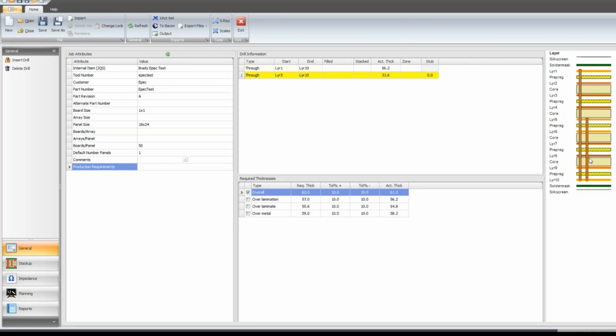You can see with the drill types, it supports different types of drills. We could do a microvia, which is defined as any hole smaller than 6 mils, typically done on a laser. Back drills and depth drills are in here. Counter bores and countersinks, slots plated. So there's lots of different types of connective structures we can put in the boards, and they're done in different processes. They may be drilled or lasered or milled or mechanically routed, but ultimately, they're all either for achieving a certain shape or for connecting the different layers electrically.